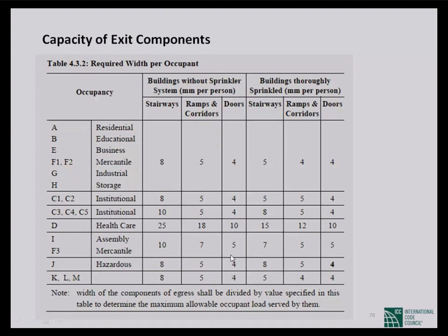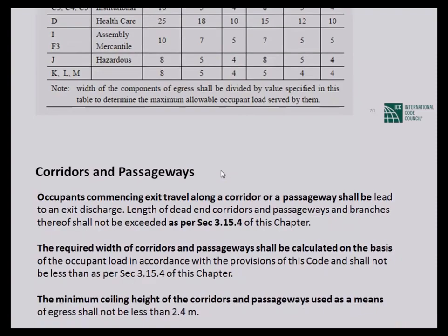It is almost double because if we consider the people coming from upstairs, the stair always has almost double the population than the level at the door, because from the door some people will go outside and some go to the stair. In the meantime, people from upstairs will come, so they need much more area. Normally, if we think about sequential evacuation, 2 floors will be coming at the time. That's why it is considered almost double in different ways.